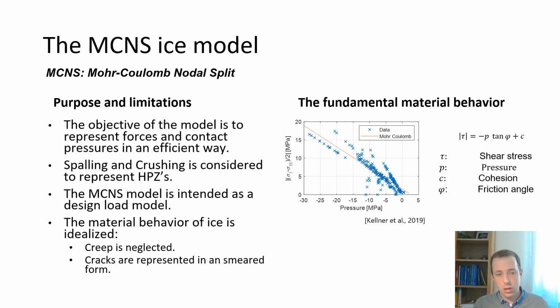We are considering spalling and crushing to represent high pressure zones, and the material behavior of ice is equalized. As we are focusing on brittle loads, the creeping is neglected, and to create an effective material use, cracks are represented in a smeared form. For example, micro-cracking or complex mechanisms like sintering or healing of the material are not represented.